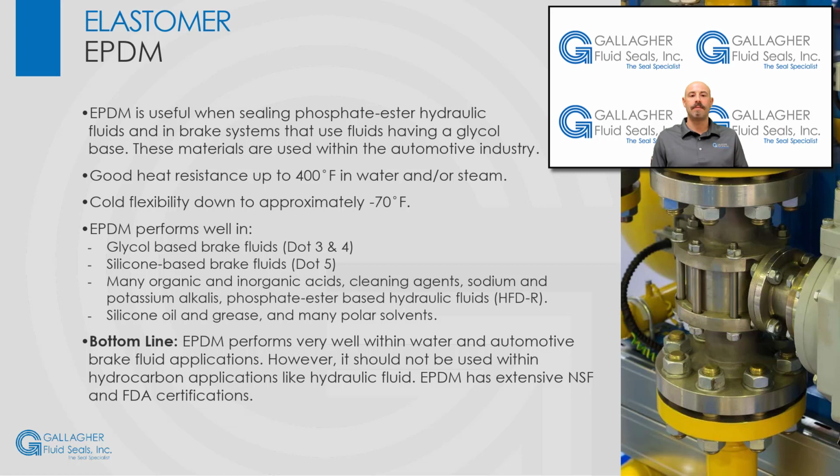EPDM offers good heat resistance up to 400 degrees Fahrenheit in water and/or steam, and cold flexibility down to approximately -70 degrees Fahrenheit. EPDM performs well in the following areas: hot water and steam up to 400 degrees Fahrenheit, with special compounds up to 500 degrees. Glycol-based brake fluids, such as DOT3 and 4, and silicone-based brake fluids, such as DOT5.